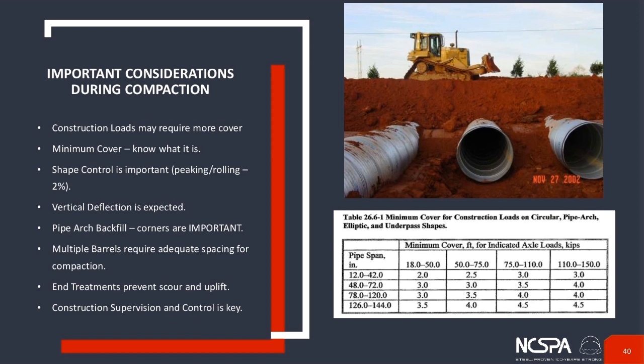Pipe arch, a large portion of the vertical load over that pipe is going to be transmitted into the soil at the corners. So the backfill at the corners must be able to provide at least 4,000 PSF of bearing resistance.